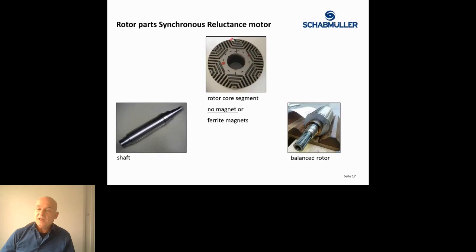One can see the thin webs next to these openings here, which are also necessary for this kind of machine design to make it work properly. But this is limiting the mechanical stability. So there's always the trade-off between what the electrical engineer wants to establish in his electromagnetic circuit and what the mechanical engineer can allow regarding stability and top speed capability of such a rotor design.